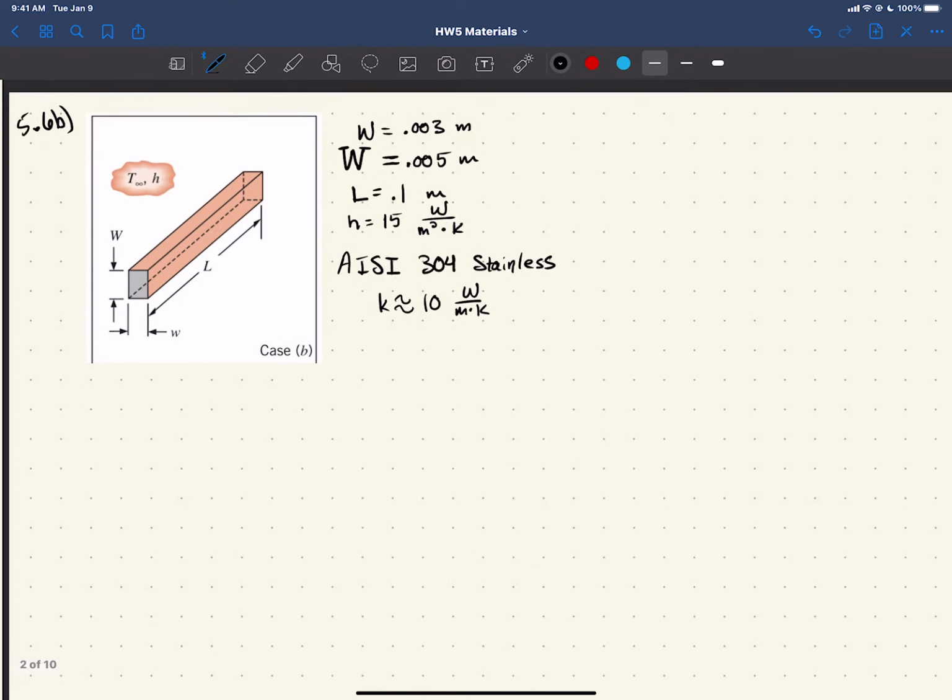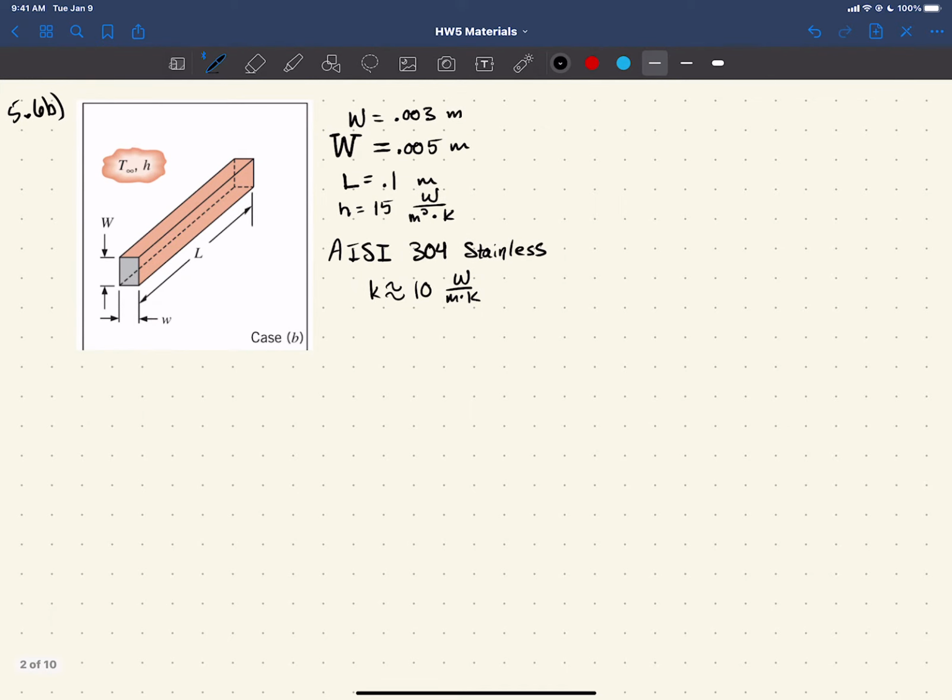So now hopefully I'm rolling a little bit, and I'll be a little smoother and ramble less. Same thing, we want to get our Biot number, h L_C over k. First, we have to find our L_C, which is going to be the volume over the area exposed to the heat transfer. The volume here is a rectangular prism, so we have little w, big W, which I put lines on so you can tell it's a capital, times L. Pretty straightforward.